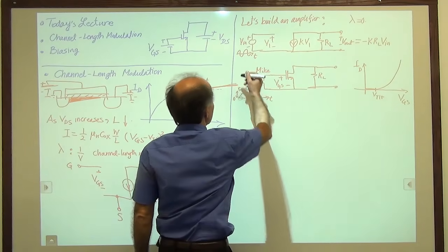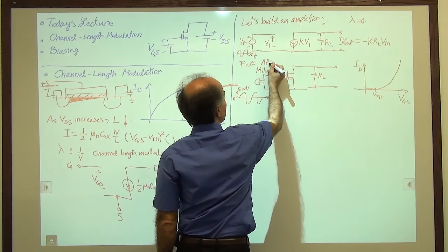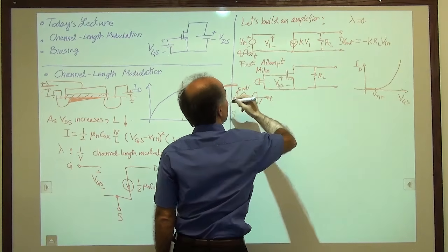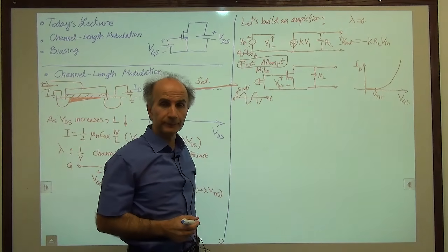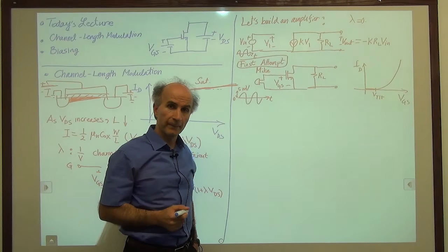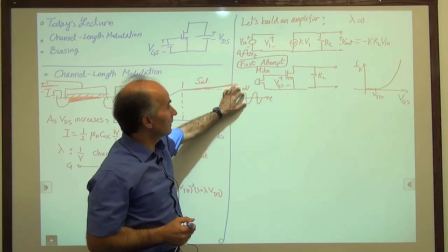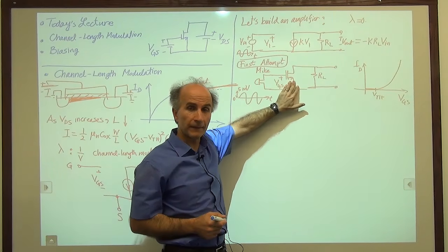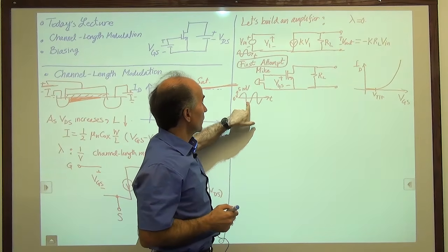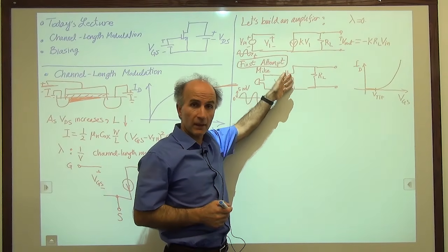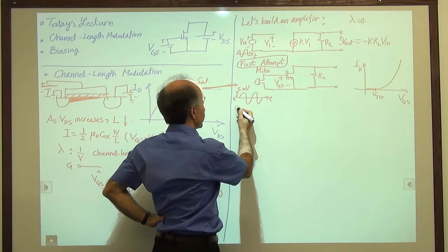Okay, so we'll call this first attempt in our amplifier construction endeavor, and that was not very successful. So what should I do? Well, the problem is that this signal is just way too small. The device is not turned on at all. So maybe what I should do is add something else to this signal so that even when there's no signal, this device, this transistor has some life in it, right? And by that I mean this. So let's go to our second attempt.